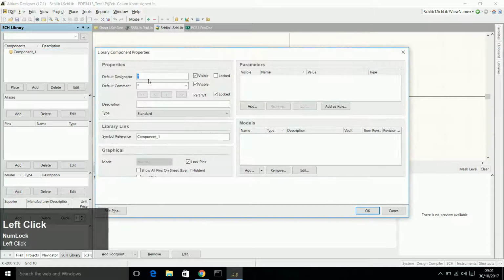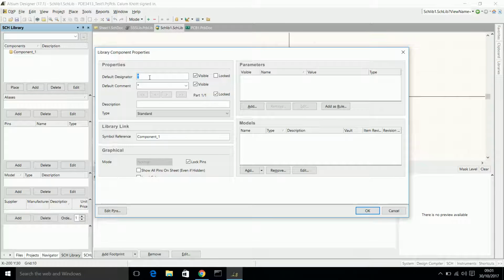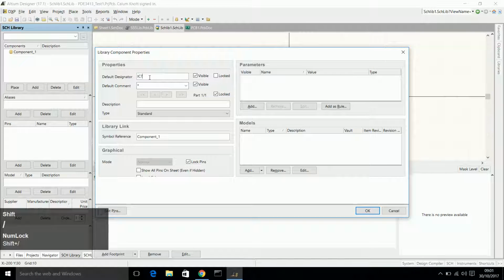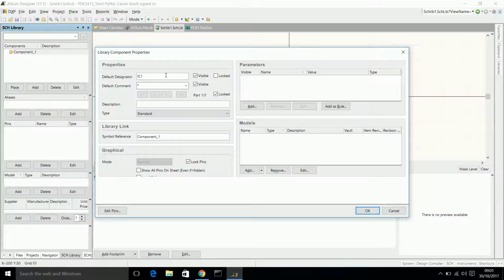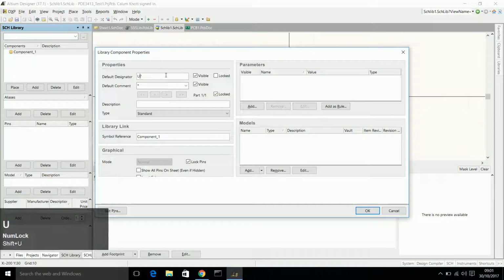We're going to double click this and we're going to call it IC question mark. You'll recall as we add ICs or chips to the board, it adds this kind of resistor question mark or IC question mark. We can call it U question mark, as is sometimes done, but IC makes sense to me. And the description I'm going to give to this is a 555 timer IC.